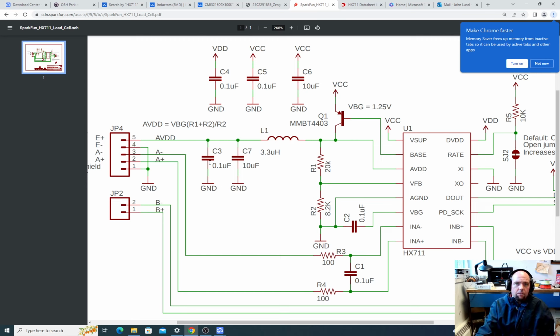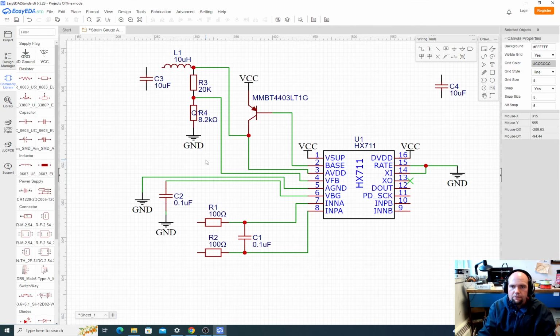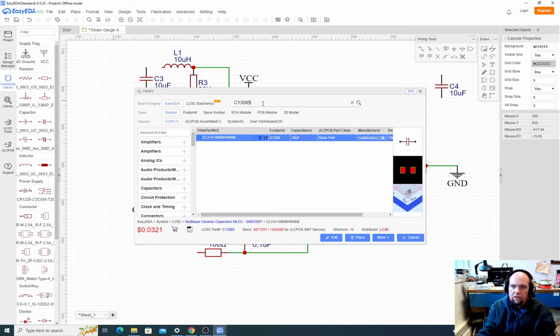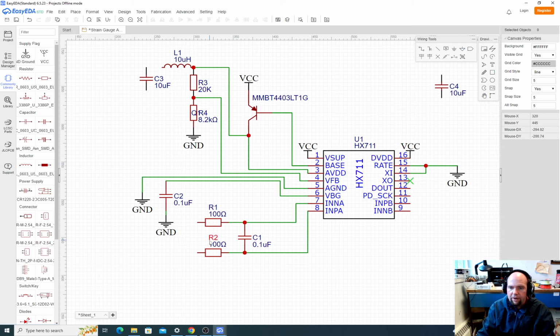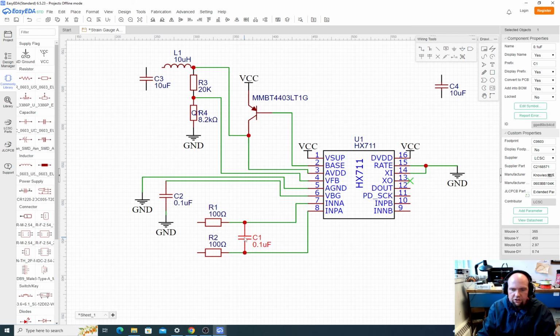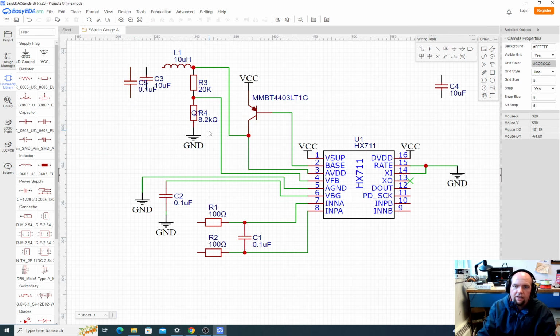They're putting a second capacitor here so that this thing filters out not only low frequencies with the 10 microfarads, but also high frequencies. So we'll do the same thing. We'll find a capacitor. Actually, we already have a 0.1 microfarad, right? We use that one here. So let's hit Control-C, Control-V, place it like that, and then we'll wire these up.